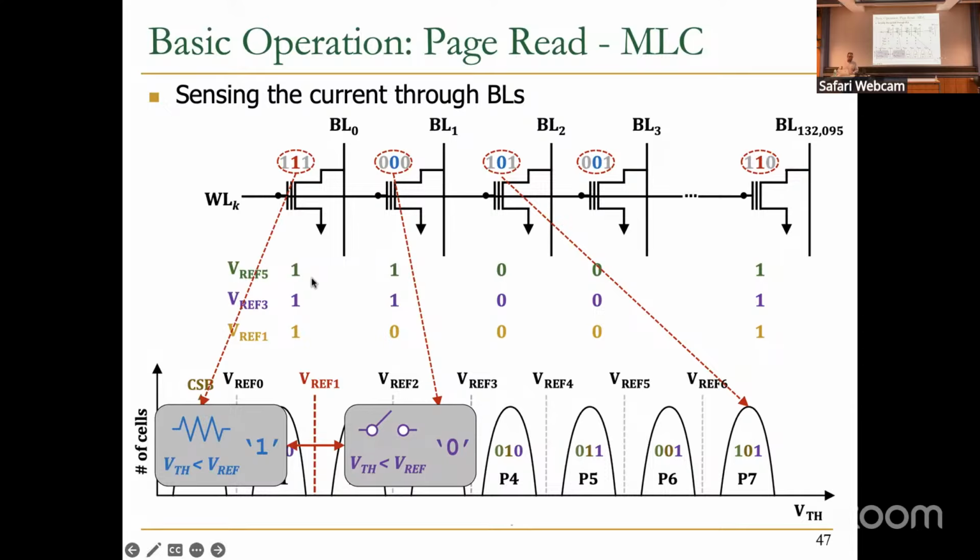With this specific encoding scheme, if you XOR these outputs, you can get the actual results. You can check it in the homework as an option as well. But essentially here you do just XORing. So XOR of this is going to be 1, XOR of this is going to be 0, 0, 0, and then 1. And with that, you read properly from this flash page.